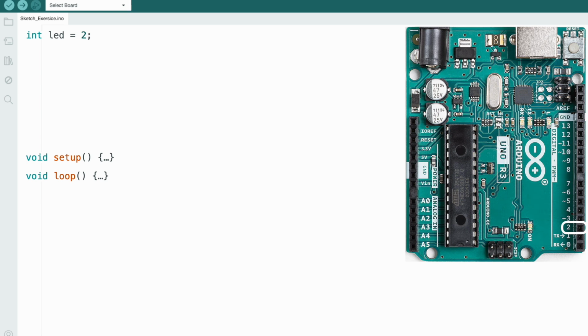And so again, looking over to the right on the screen, looking at the board, these are the pins that we're going to be writing out to. And like I said, we're going to be reading in from pin 8. Pin 8 is what we're going to be reading in the tilt sensor from, and pins 2, 3, 4, 5, 6, and 7 are what we're going to be writing out to.